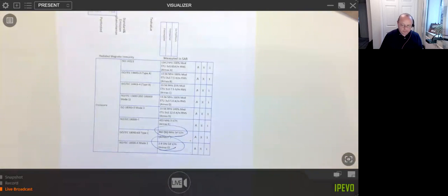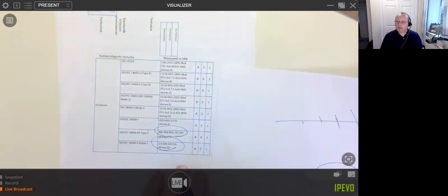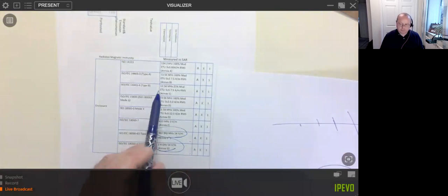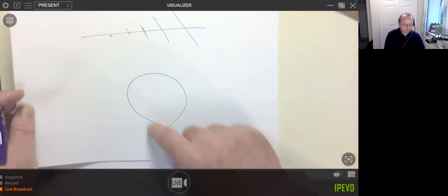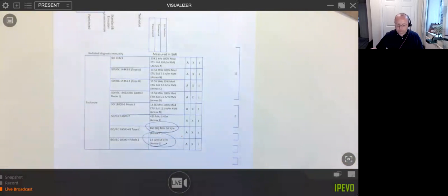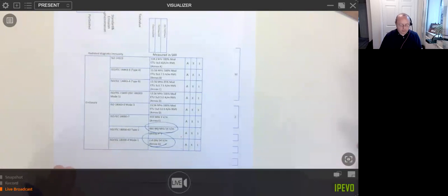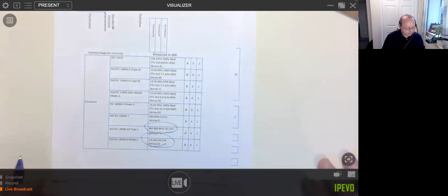I am told by the people at the EMC test site that they have never seen an issue under the electric fields, which is this funny loop thing. They've never seen any issues with that, but they've certainly seen plenty of issues with the radio waves. And sure enough, we had our fair share this week. So hopefully we're going to get back in there on Friday and see if this idea of putting a proper ground plane on the Flexi Track saves the day.